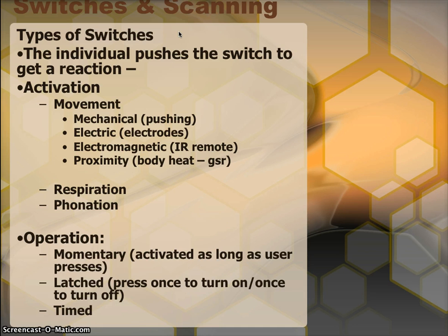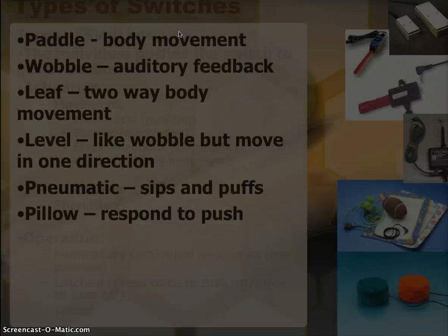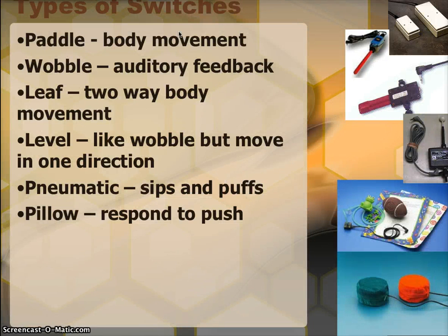Operation. Switches can operate momentarily, so as long as our hands press down on the button, it will operate the switch. They can be latched, so you click on the button once, and it'll keep going until you click on it again, and it'll turn it off. It can also be a time switch, so you press on the button, and then after a certain set amount of time, 5 seconds, the switch will turn off. Many different types of switches out there.